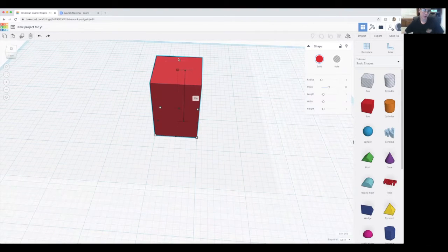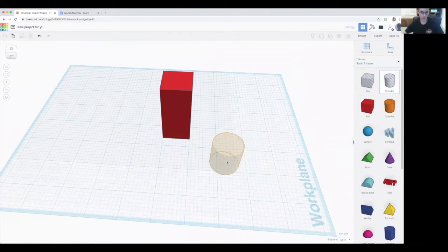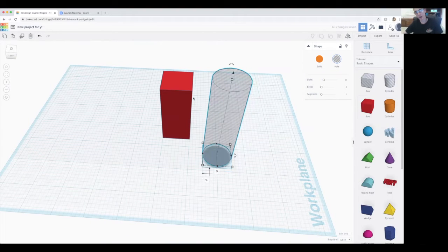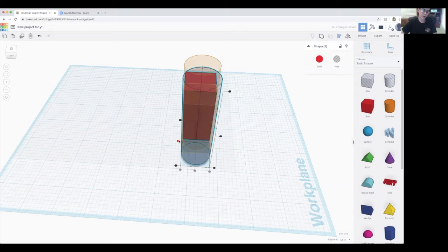I could stretch this up to be 2 1/4 inches. Go over here, I grab this circle. I want to lift it up about 1/8 of an inch, and I want to lift this up so it's very wide. Now see, how do I get them to be exactly aligned? I hold shift while selecting one and I click on it, or using the left side of the mouse, I do that. I hold it and drag it. Now I click on this align button. I can do this so that they'll move around like that.